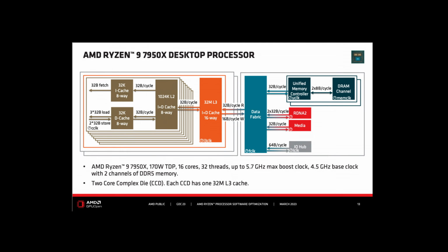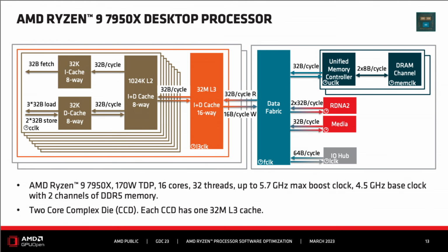This diagram shows the memory communication path used by Zen CCDs. The slide is from Zen 4, but the Ryzen 9900X on Zen 5 uses the same fundamental structure. And the key to understanding its memory behavior is in these 2 yellow highlighted links. Let's start with the first one, between the L3 cache and the Infinity Fabric. This is the path every cache miss takes when data leaves the core complex, and importantly, this link is asymmetric. One side can move 32 bytes per cycle while the other is limited to 16 bytes per cycle. So even at this stage, the data flow is already constrained before it even reaches the rest of the system.